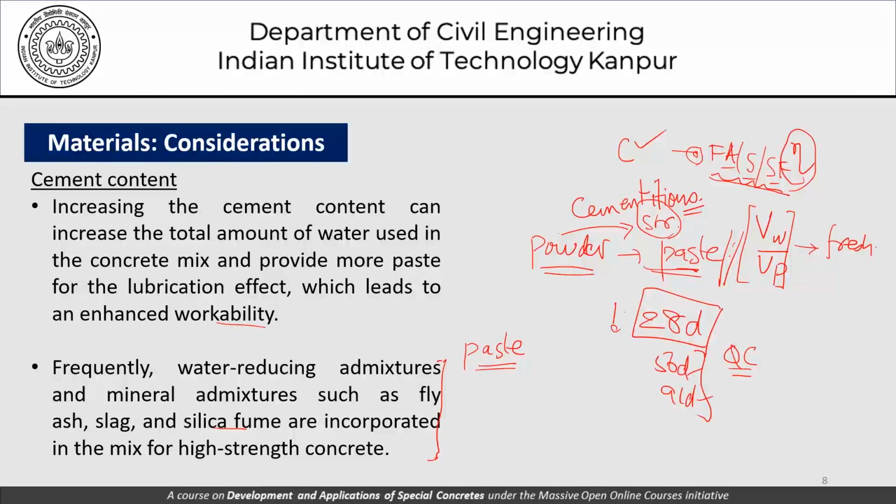So that's the essence of our discussion in this entire series of lectures, that for special concretes, there are special considerations, and something like 28 day is good for normal strength concrete. And there is no reason to stick to this as if it was etched in stone when we are talking about something like high strength concrete, where we know that the choice of materials is such that strength development may continue for a longer time.